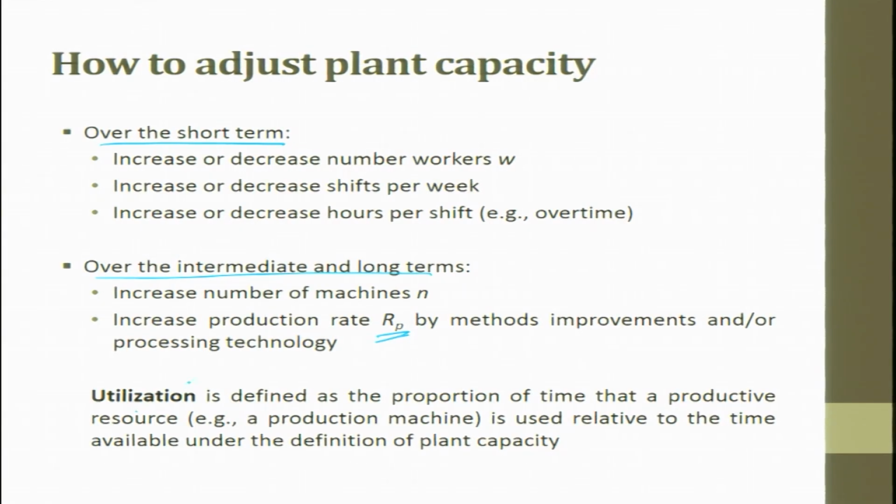For example, if the machine is used 60% of a shift time, which is 8 hours, you can calculate 60% of 8 hours. Half of it is 4 hours, so it should be approximately 5 point something hours that you operate the machine out of 8 hours. For the rest of the time the machine is idling, waiting for parts or tool setting. So, this is nothing but the utilization chart.